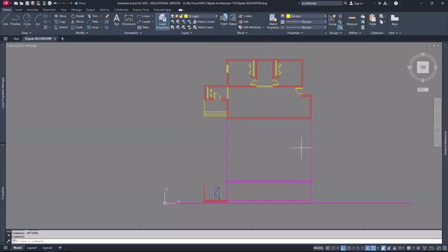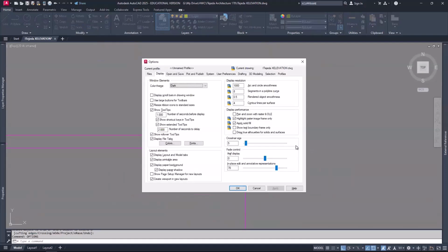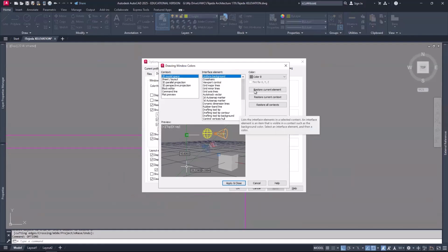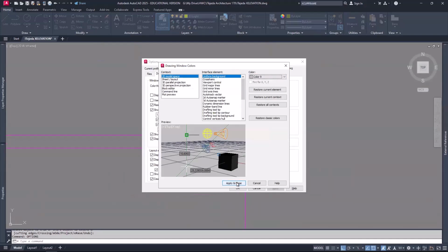So I don't need the lines here to be extending so far up. So I'm just going to take that, grip it, move it down here, tap the escape key. Do this a little different. I'll type TR, enter. I'll trim here and then I'll trim there. All right. Then let me zoom in over here. And yeah, I got to do one thing over on my end. Sorry, I need to look at my colors because that color number 8 might not be the best. So if I go color 9, let's see.